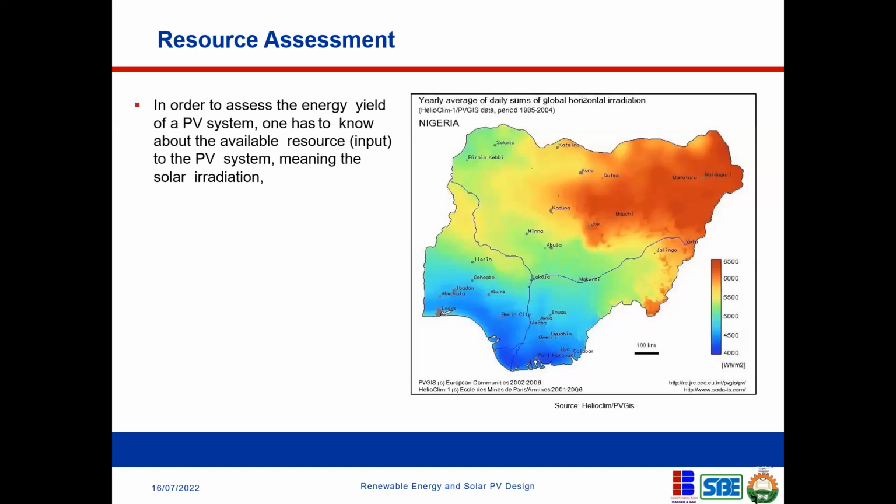So if you're doing a project and you have the option to choose between these 3, thin film solar panel becomes more attractive for the north. However, it has a lower efficiency. It has a lower efficiency to convert sunlight to electricity. But in terms of temperature tolerance, it is higher.